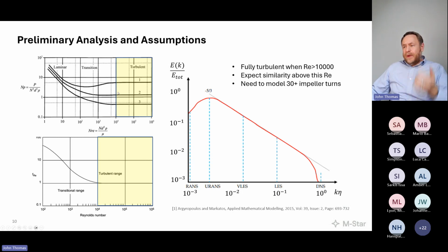That would give me compelling Reynolds numbers and turbulent systems for both agitated systems and the pipes I'll speak to momentarily. When I need to be able to run an agitated vessel, it's dozens of impeller turns, right? If I'm really trying to predict EDR, I can't just do one turn of an impeller and claim that I've done DNS. I need to run dozens, hundreds of impeller turns in this higher Reynolds number regime to really convince myself that I'm doing a proper simulation and DNS at that.